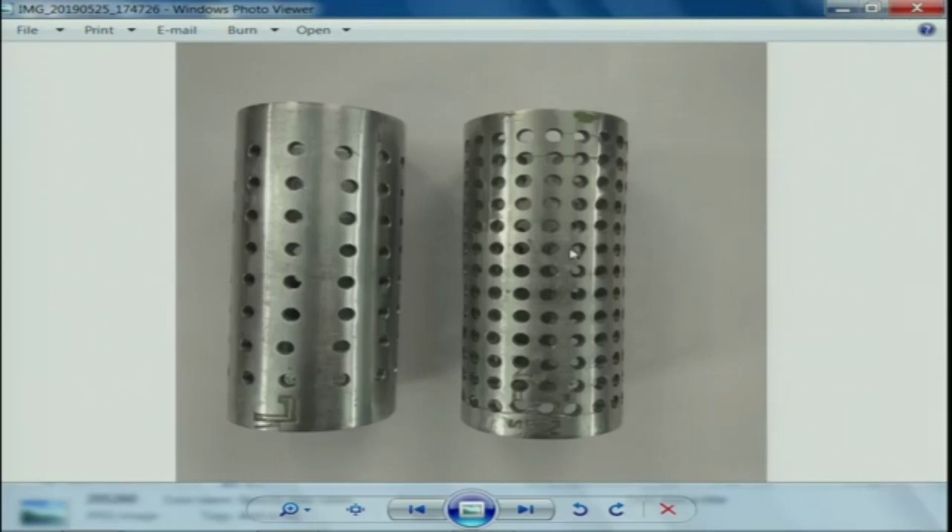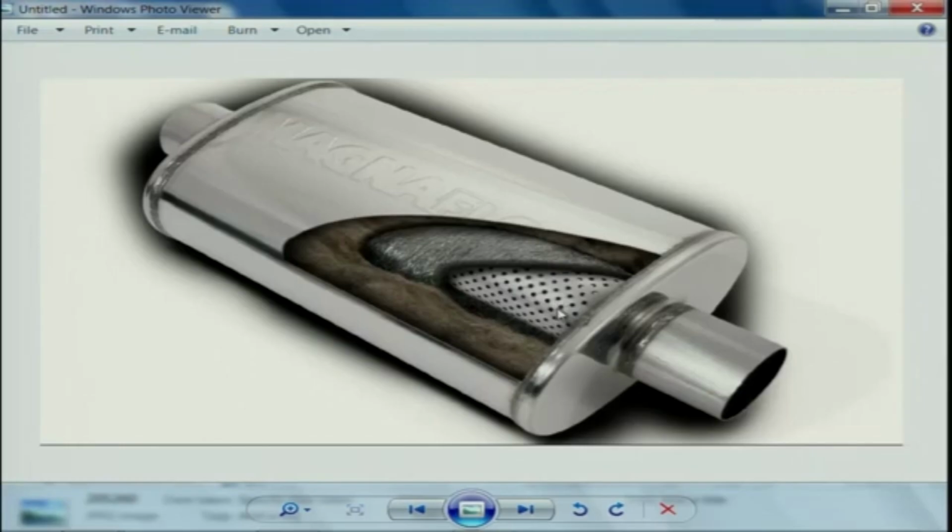This is definitely highly porous, because porosity is about 28 to 30%, somewhere between that, and this is only about 12%. The final thing that matters acoustically is the transmission loss of a muffler, which is highly dependent on the porosity. We did some experiments some time back and figured out that this is highly porous, and this is as good as acoustically this being not there, but the presence of such a perforated thing is very crucial, because of what will eventually happen.